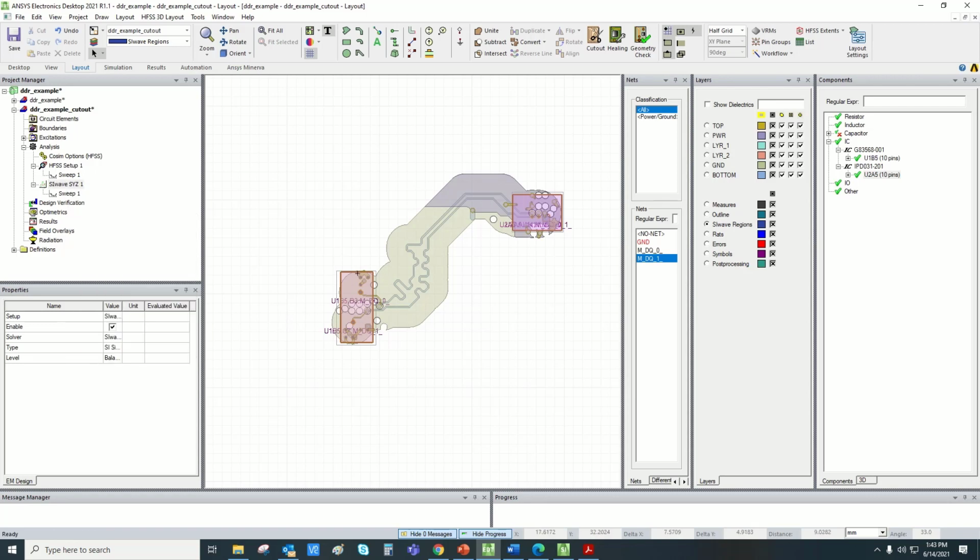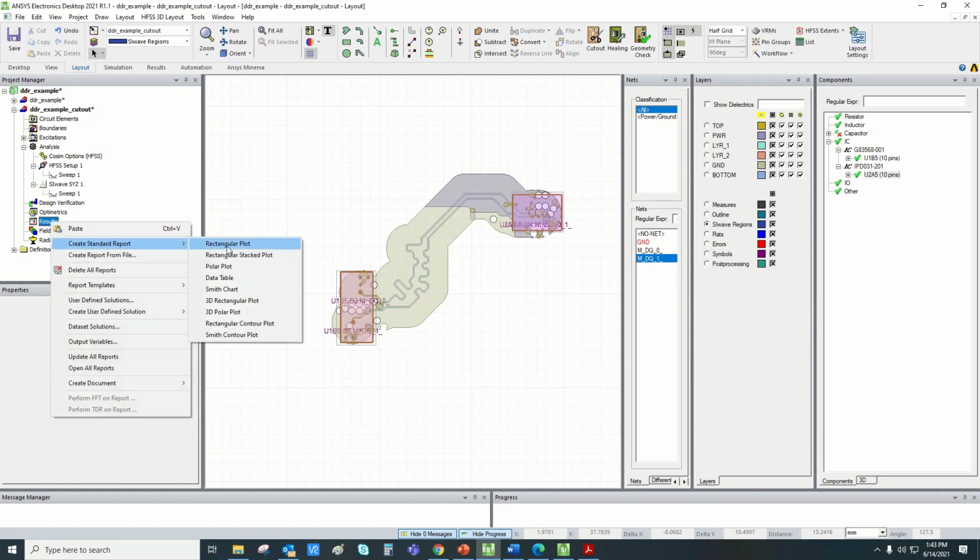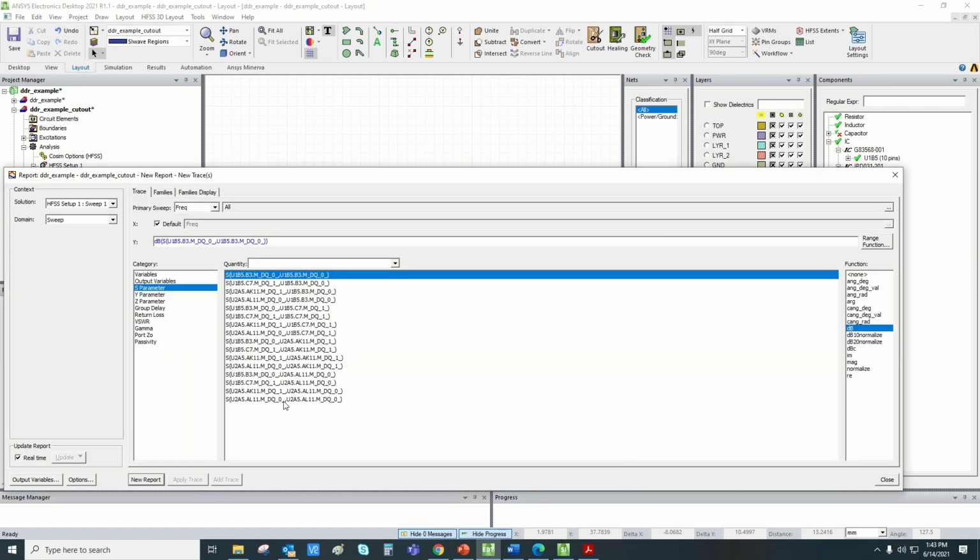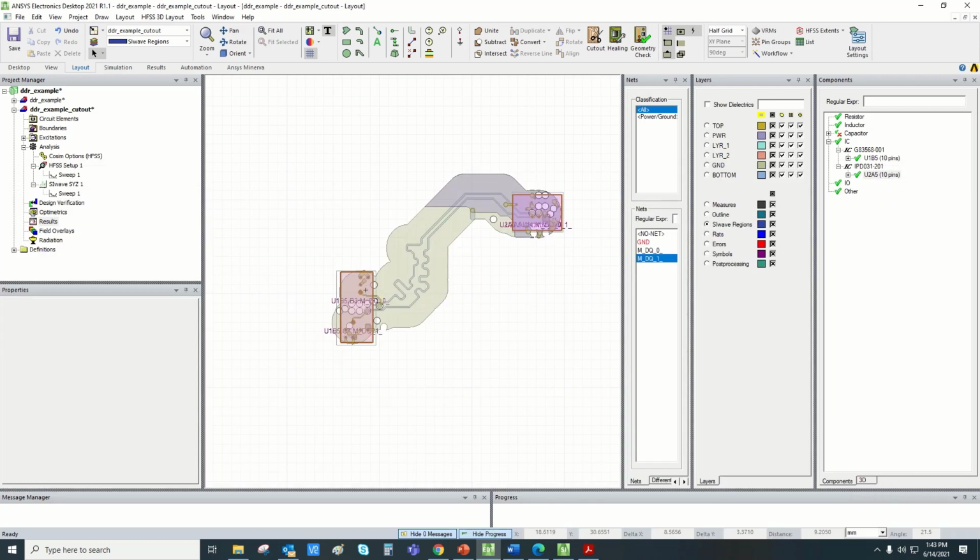and then it will solve the IC component regions using 3D solver and the other regions using a 2.5D solver, and then you can plot the results, and the results would not be different for each region. So it will be a cumulative result for these two regions, as well as cascading the S parameter of this. So the S parameters which you see from here would be basically your end-to-end full S parameters. Okay, so the S parameters would not be basically different for each region, right?